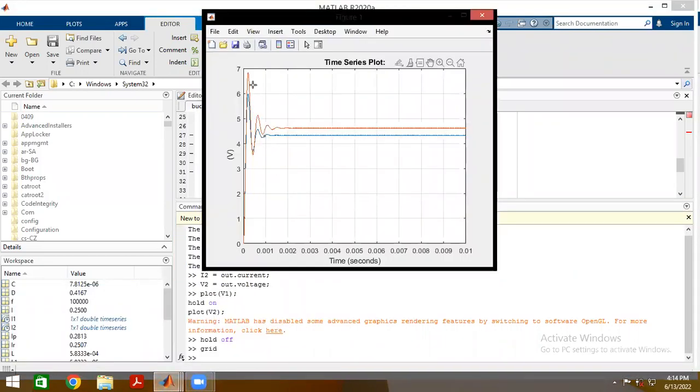That's better. So what we notice firstly with the initial run, that is the blue curve, we don't even reach the 5 volts that we initially designed it for. We're only getting to about 4.3 volts. With the lighter load, the 20 ohm load, which is the orange plot, our voltage is a bit higher. It's about 4.6, but still, we're not reaching what we designed it to reach.